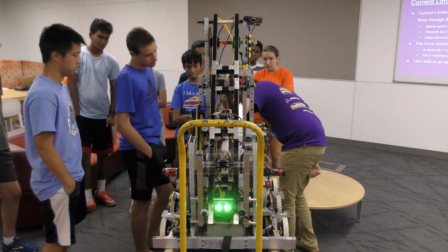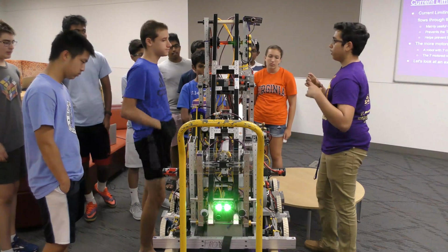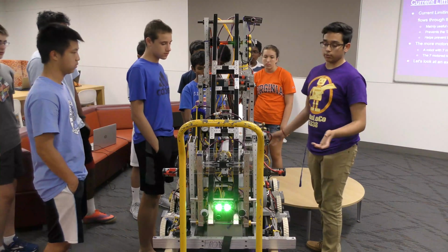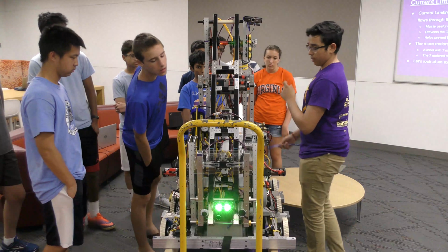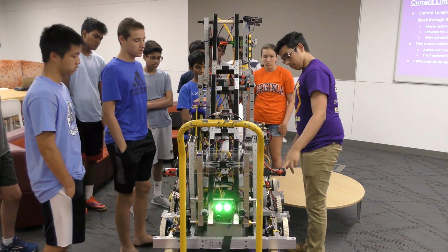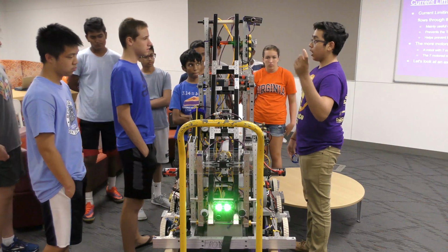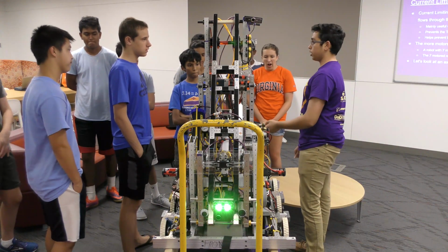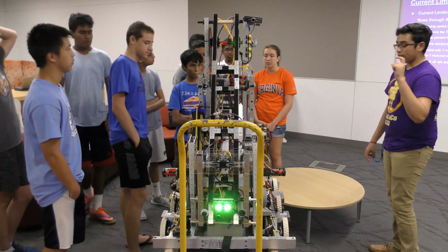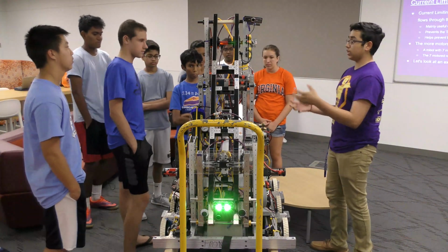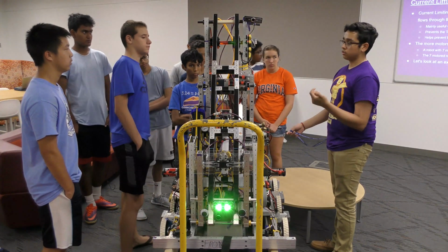And then there's the low amperage circuit, which are the ones back there, where you have the stuff that doesn't need that much electricity, like the light up here, so that stuff goes on the low amperage. When you have a lot of motors like we did this year, you have to put motors that might require high amounts of power on the low amperage circuit. So that's where current limiting comes in super well, because you had to make sure that it didn't draw too much power and pop the breaker.